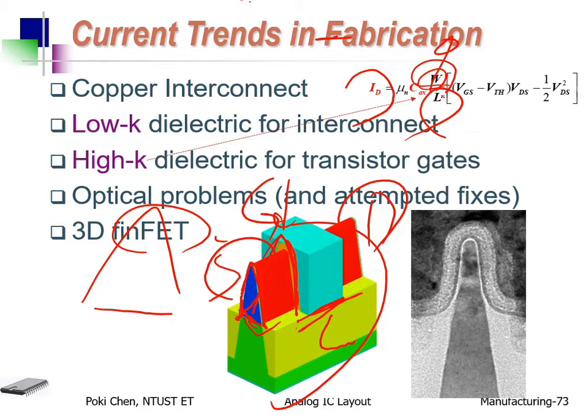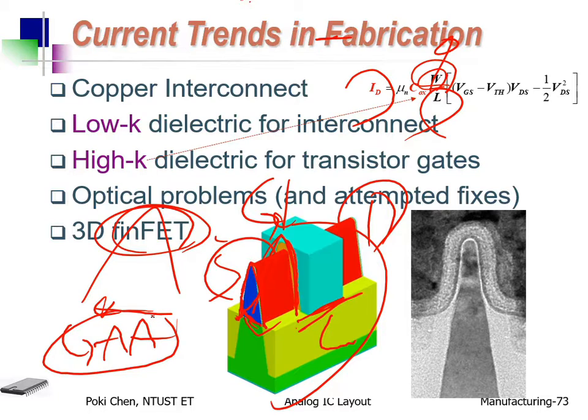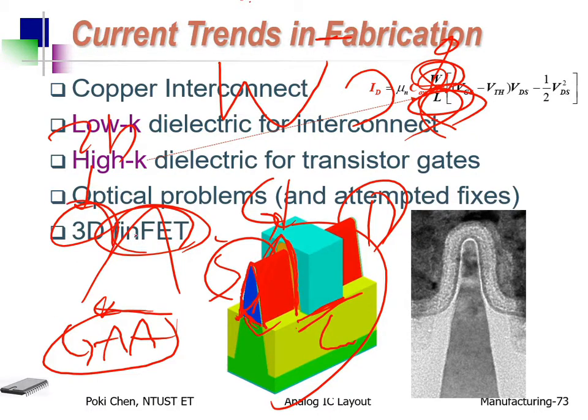We would like to enlarge the width. That's it. From 2D to 3D. Then, from FinFET to gate all around, again, because the length was already minimum, from 2D to 3D we enlarge W, and from 3D FinFET to gate all around, we further increase W. No secret. Later I will go to the end of the three-dimensional plot and make it even clearer for you.